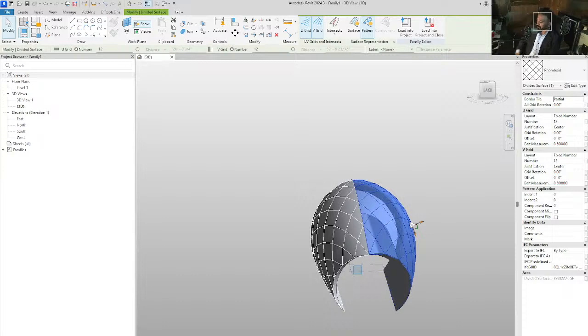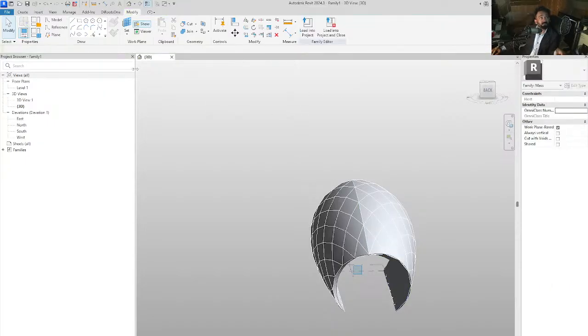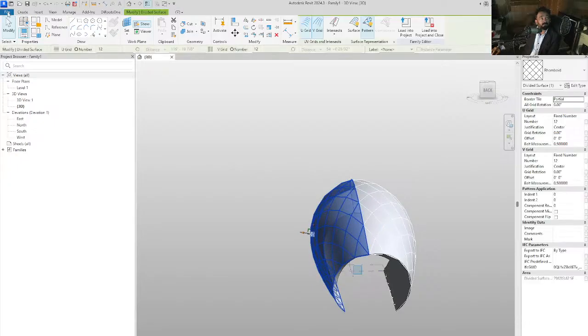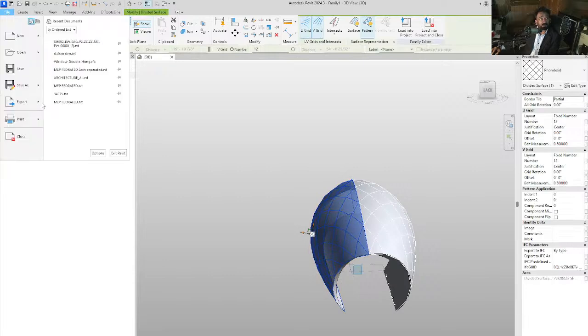We check how to make the division, and in this session we will actually create something for the main division. Within the division we will make a parametric custom family. So what we have to do is, in the massing we do not need these shapes, we need specifically some facade elements to design. So for this we have to use a generic model family.